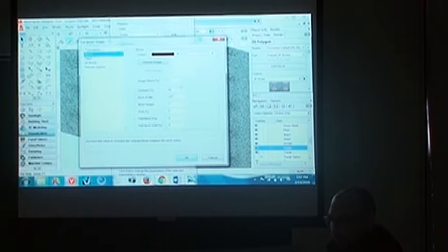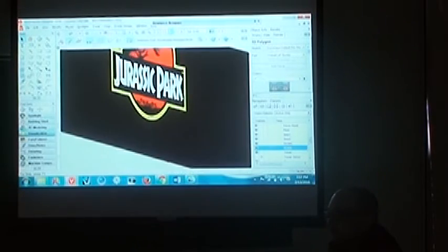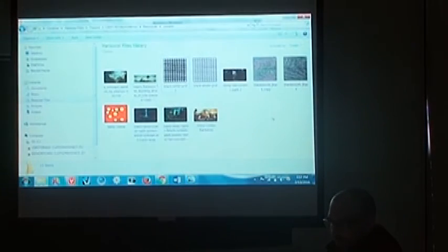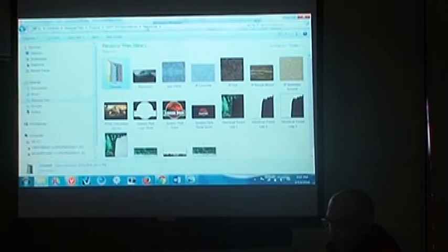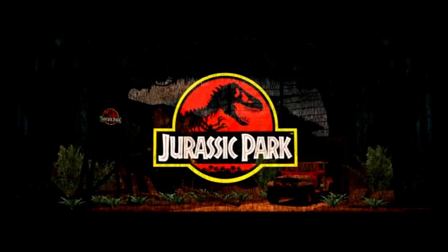But basically I ended up with black and white, 40% contrast. My brick width is 1/2 inch, the height is 1 inch. The gaps between are 1/2 inch, still black and white, and this is what the noise is set to. And by using that for the transparency instead of an image, I was able to get something that looks like this.